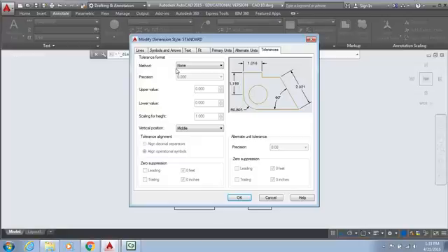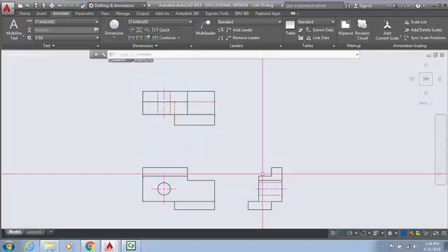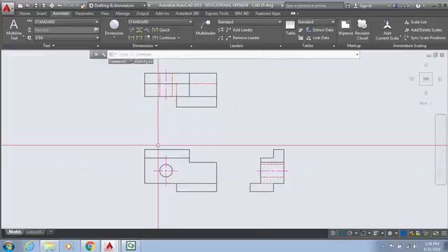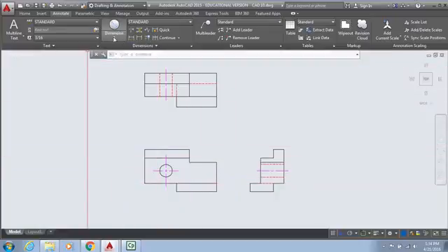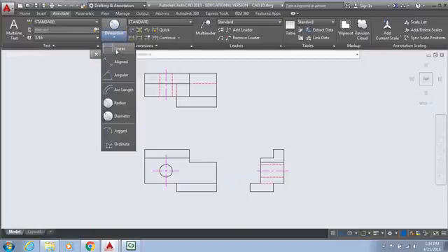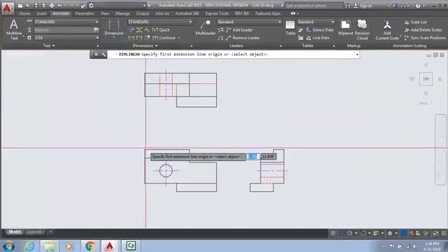So when the time comes, I think in CAD 12, maybe, we'll start putting some tolerancing on a drawing. Show you how to do that. Hit OK. Hit close. Now basically, all you have to do is copy the dimensions as they exist on the print. So if I want this overall 4.26, you can hit the dimension. It's a linear dimension, and you want to click.